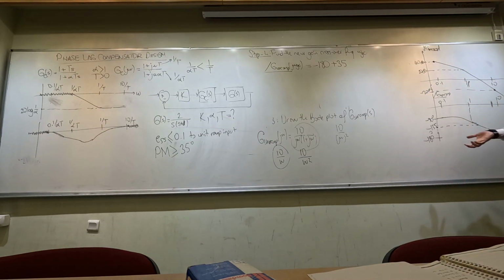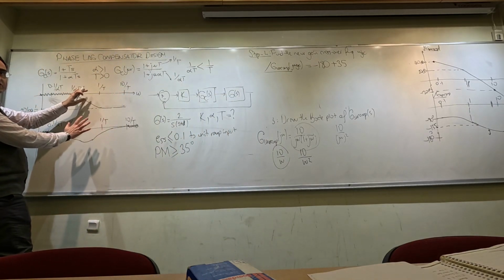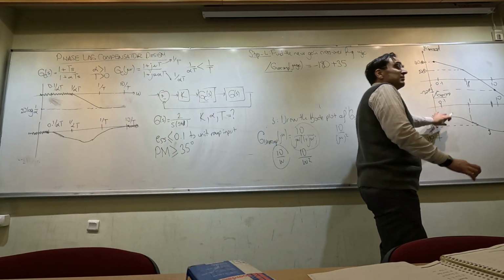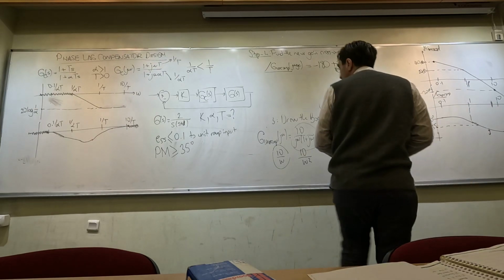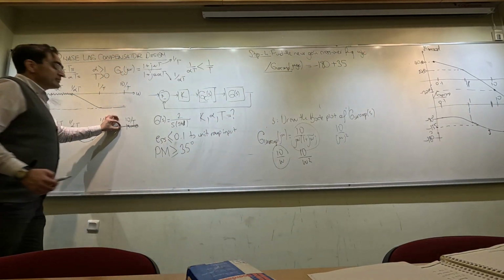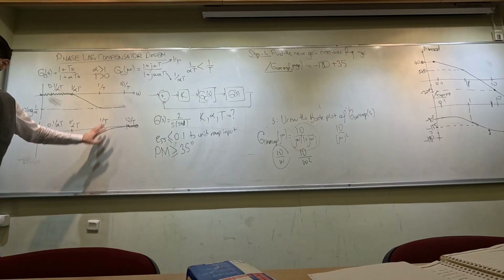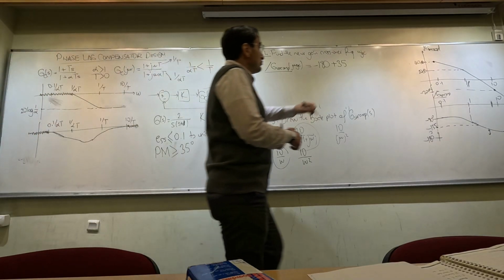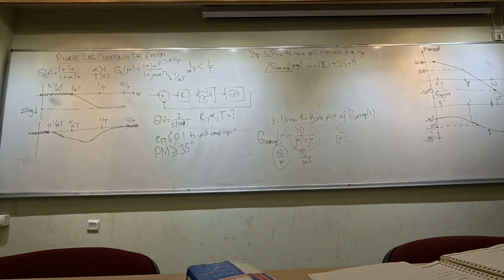But here, as I told you, I will try to push this transfer function as much left as possible, but I will not let it go to minus infinity on this plot. Okay? So here, there might still remain a tiny negative phase that is going to be added by this phase lag compensator. That is why we usually add just a 5 degree error margin here. Okay?